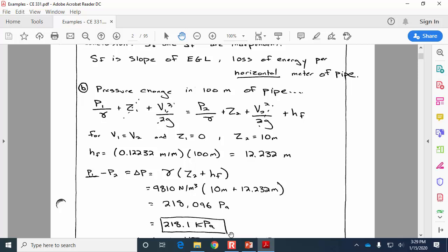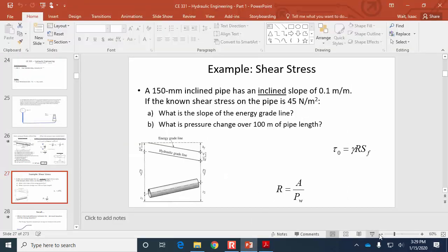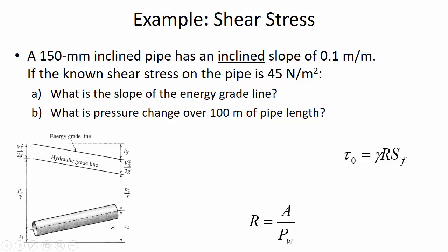And the pressure that's downstream is different for two reasons. You'll notice that location 2 has a higher elevation, so it's going to have less pressure, partly because of the elevation change, and partly there's going to be a pressure difference due to pipe friction. But both of those are heading in the same direction. Both of those mean that the pressure will be lower at location 2. Lower because it's higher in the fluid, and remember the hydrostatic equation says if you go down through a tank, the pressure goes up. If you move up through a fluid, the pressure decreases.